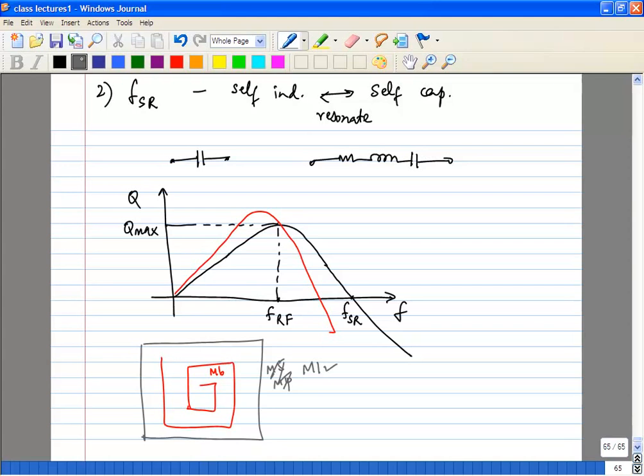Okay? Can you do even better? Okay, so you can actually use your poly layer, right? So let's say you can even use your poly layer. Poly layer has a slightly higher resistivity, but you can use your poly layer. So that is another conductive semi-conductive layer between your inductor metal layers and your substrate. So you can use your poly. So that is another option.